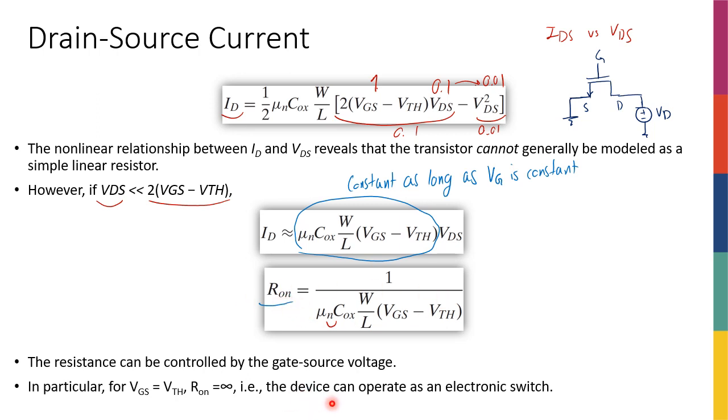This is the reason that MOSFETs are really good for digital. This is the region of operation that we use MOSFETs in for digital electronics. The entire field of digital electronics, and whatever you have heard about digital circuits, is based on simple switches that should be turned on or off. You have seen switches in electrical circuits before, that we show with this symbol. If this is X and this is Y, we could have the switch on and off, right? The switch could be simply created by a MOSFET